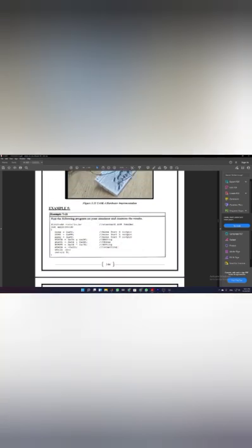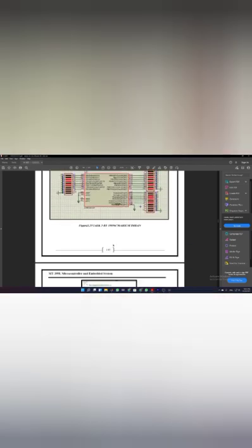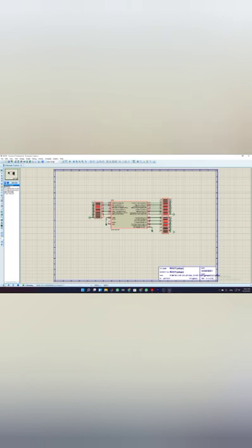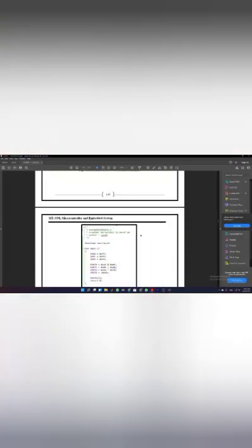Now in example number 5 we have to run the following program, simulate it, and comment on the results. You can see that DDRB is declared as output, and now we'll move on towards the next one. You will see that all these ports are just illuminated with the LEDs, because in the previous code we were provided with a code that has no input. All the 3 LEDs were working as an output, so we have disconnected it like that.